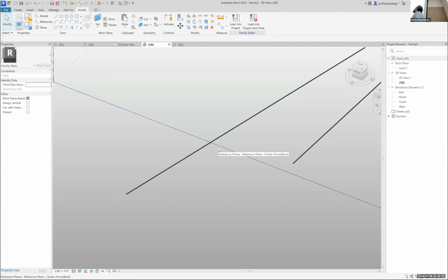Okay, so when you're locking on there, this is what's interesting. There's the repeated nodes, right? The divided line, which is hosted on the line. The line is really on point. So that point, there's both the endpoint and the divided line there. That makes sense. They both exist there. So I tend, when I want to lock something in that's going to repeat on a divided line, to make sure I go one in because it's going to repeat anyways. I don't want to accidentally grab the end. It happens a lot within the pattern, but that makes sense.